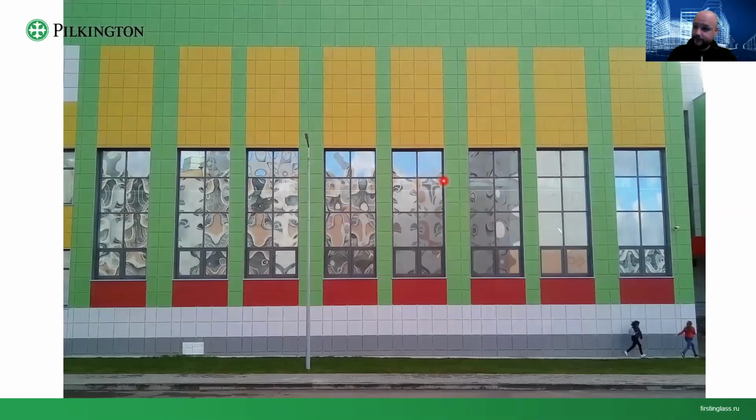But the first thing that you will notice, the glass will not break, but first you will start to see the optical distortion on the facade. So here is a very good example of how the facade can look quite bad if the IG unit composition was not properly chosen. But I've covered this in the 3-part webinar. You can go on the YouTube channel and take a look at it. It's called how to design an IG unit.